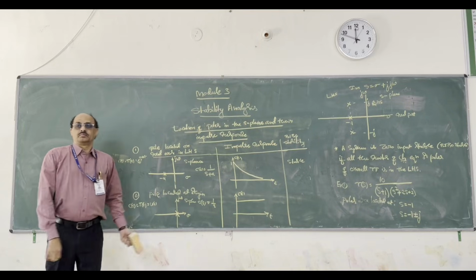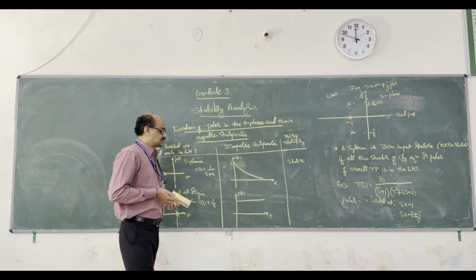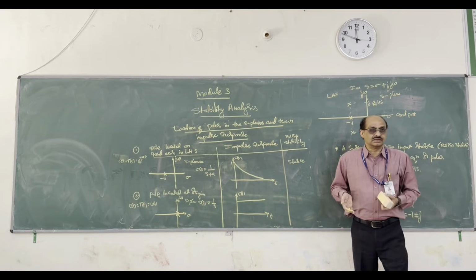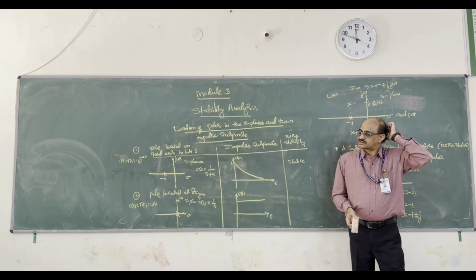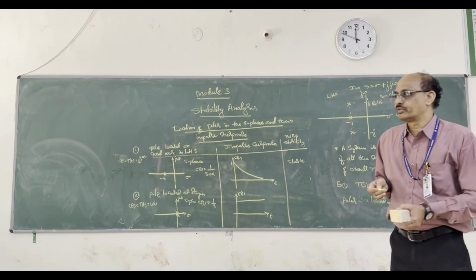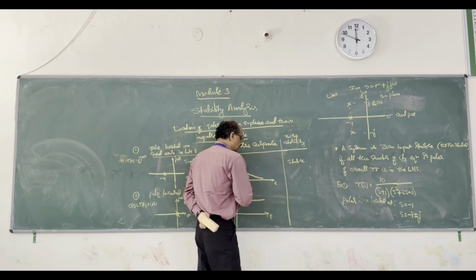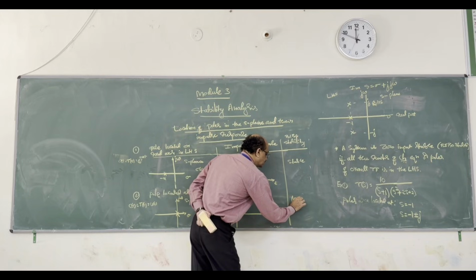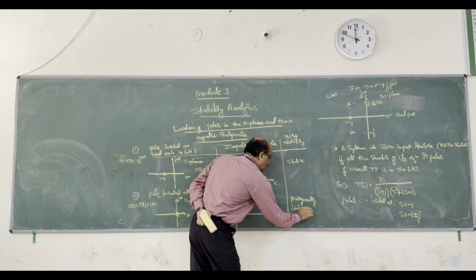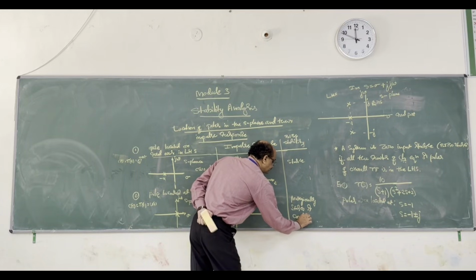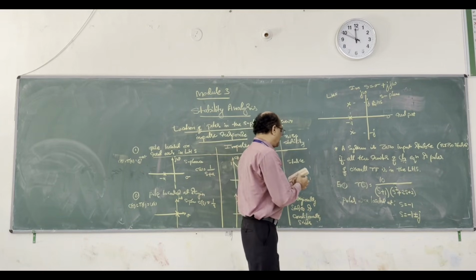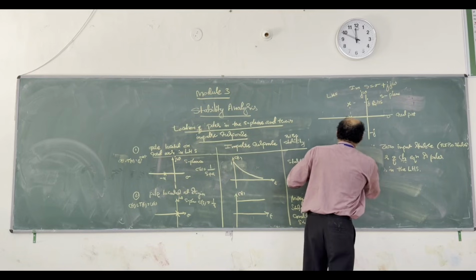The magnitude is not decaying, so obviously according to BIBO or zero input stability, it is in fact unstable because of constant magnitude. But in control systems, we usually say this is marginally stable or conditionally stable.